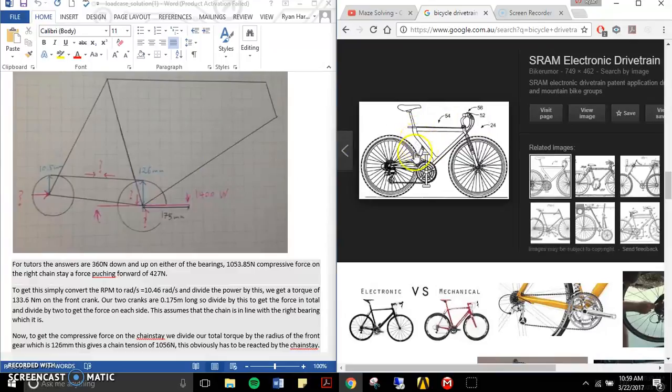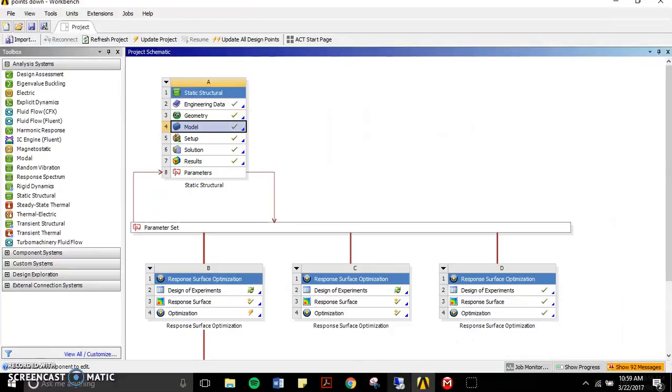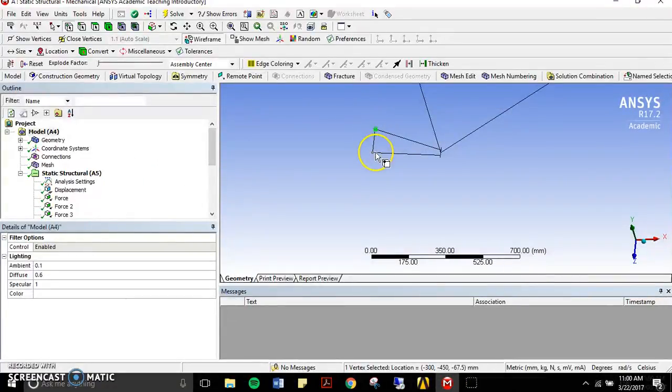So these wheels, right? If you sit on a bike, and the bike is being held up by whatever, assume that you're extremely good at balancing. What kind of reaction are those wheels applying to your mass? Well, they can only apply a reaction in the vertical direction. And more than that, the two dropouts, the two points at the rear of the bike, this one and this one, can rotate about the center point of that axle.